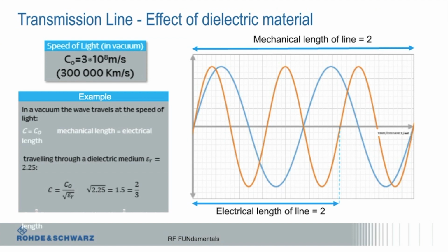Then you go and get a Gore flex, air dielectric, and now it's 40 dB after calibration. So, the key thing to remember is you can vector correct it, but you're more or less establishing a noise floor based on the worst case VSWR of whatever is in there. It's a great question, though.